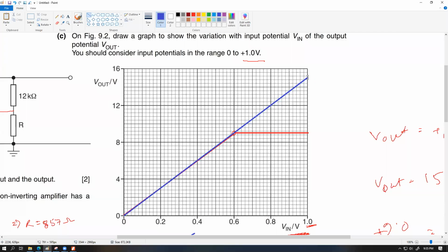But sir, then if my V gain was more than 15 volts or less? Which one? What do you mean V gain? I mean the gain in voltage. Output? Wasn't the gain 15 volts here, sir? Gain is not voltage, gain is a number. Output voltage or input voltage is in volts. Gain is the multiplication factor by which your input will become magnified. So in this case, gain was 15, yes.